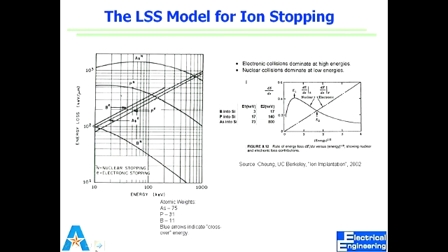As a process engineer, now you have to know this. Probably you won't do anything because there are set recipes that we use. Recipes tell us, okay, use this kind of energy, this dose, this voltage, this thickness of your mask material, and how deep and of what concentration you will get. So these are very well defined. If not, you characterize your equipment and you come up with those, right? So this is the physics behind how these differ for different types of dopants.